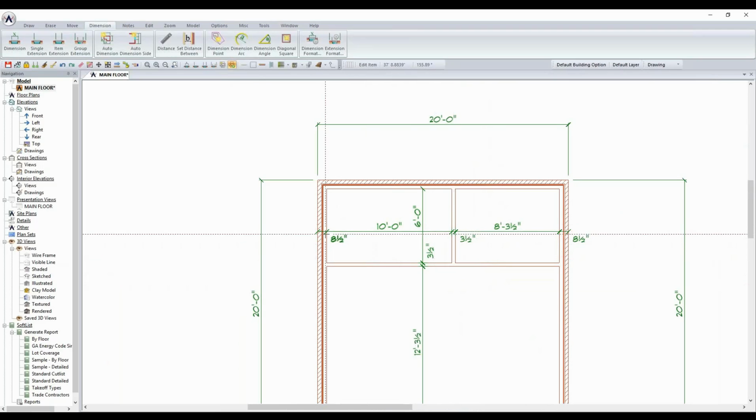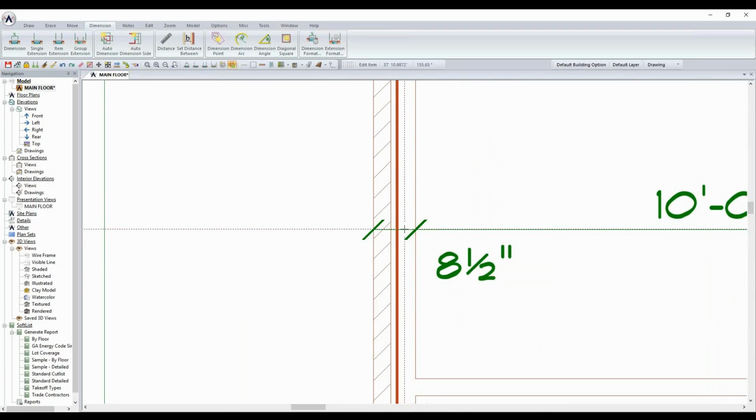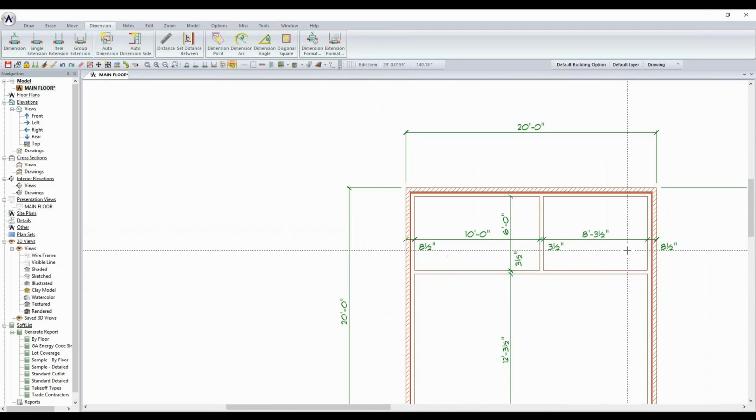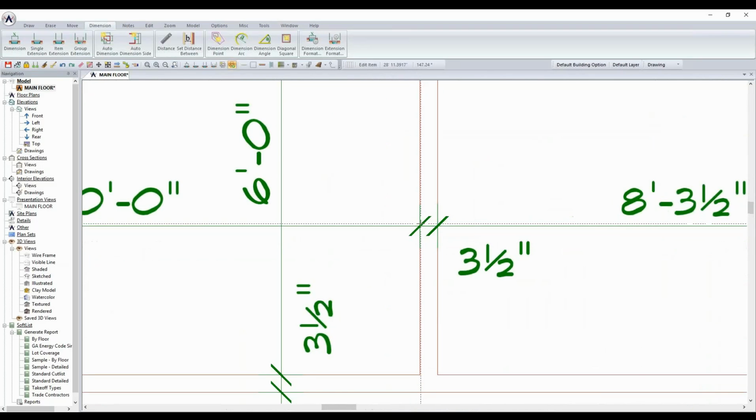You'll also notice that our extensions are currently going to drywall and outside of brick. On the interior walls, we have it set up to go to the stud region, so it's showing a 3.5-inch wall, meaning it's ignoring the drywall that is actually part of the wall, just not visible on either side of this. That is your choice. You can set your wall definitions up and customize them so that it goes to the exact spot where you want it to go.